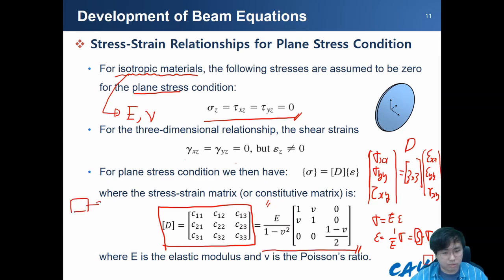When you apply some external force in the x direction, the length is elongated, but due to the Poisson effect, the lengths in the y and z directions shrink. So the strain is proportional to the compliance of the x direction, but for the other part, because it shrinks, we need some minus.